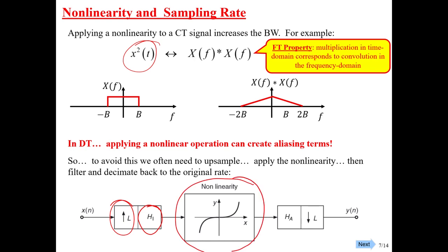So let's think about what that would mean. So at this point here, our sampling rate now might be out here, so that our Fs over 2, and maybe I should put a prime on that to show the sampling rate that's here after we've increased it. Now that's going to be all the way out here, Fs prime over 2. No aliasing happens.